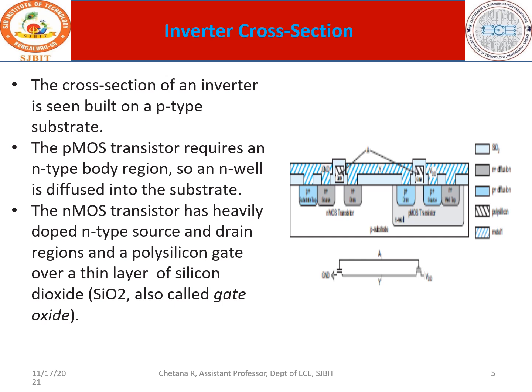Similarly, if you have an N substrate, you can construct PMOS transistors. A PMOS transistor is the one which is constructed on an N substrate. So this is your P substrate, and since I have already told you that this is a P substrate, it is possible for us to construct two types of N terminals here, N diffusions, and therefore an N type of transistor. This becomes your NMOS, this becomes your PMOS. And do the necessary connections, that becomes your inverter.